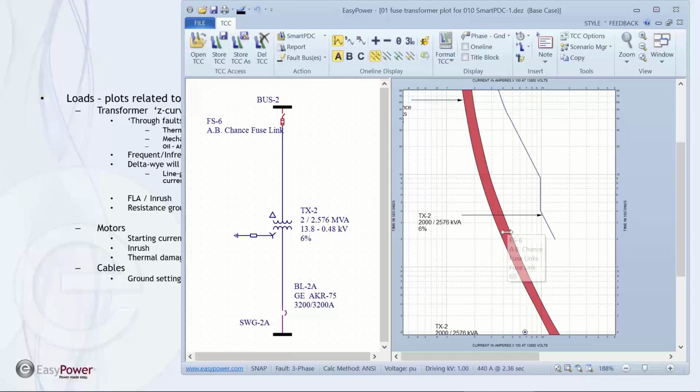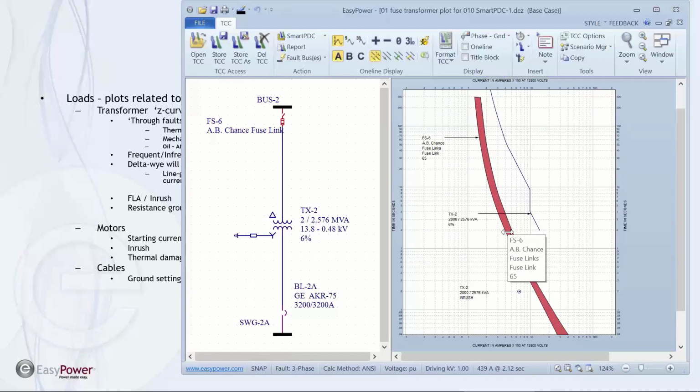The width of the fuse itself is based upon the manufacturer's spec and tolerance level between the lowest sensing value and the upper fusing or clearing time of a particular fault. In terms of what we want this fuse to do, we want it to protect as much of the transformer as we can and still allow the full load current to be available on the secondary side.